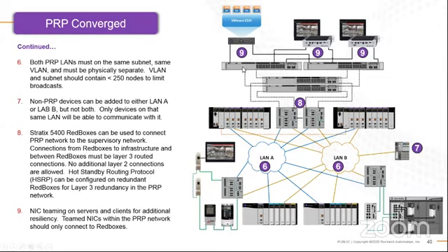The big change over here, as you guys have seen, device level ring has a 3 millisecond reconvergence time. So if you lose a network connectivity, it fixes itself within 3 milliseconds and you go to a linear network. Parallel redundancy has 0 reconvergence time. Essentially, it is a bumpless transfer. So if you lose a cable, you lose anything within LAN B, LAN A was still communicating and sending the data actively on both ports. So that is the big change.